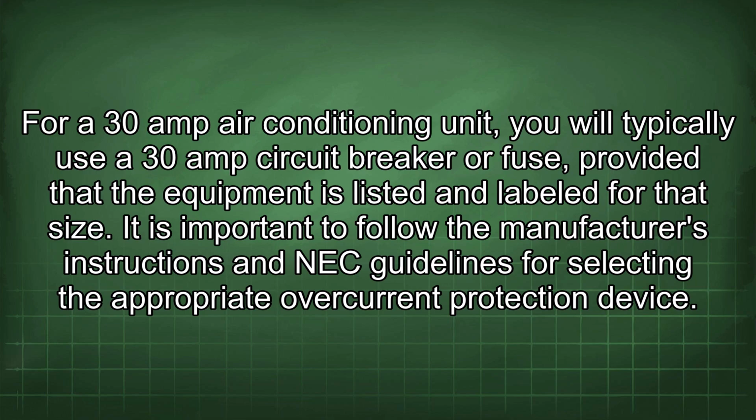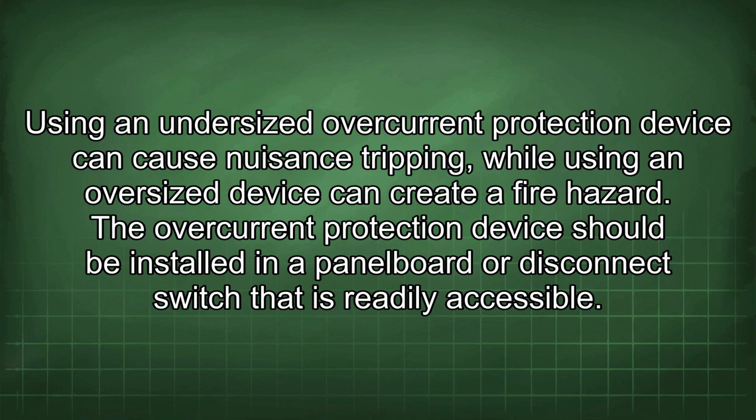the equipment is listed and labeled for that size. It is important to follow the manufacturer's instructions and NEC guidelines for selecting the appropriate overcurrent protection device. Using an undersized overcurrent protection device can cause nuisance tripping, while using an oversized device can create a fire hazard. The overcurrent protection device should be installed in a panel board or disconnect switch that is readily accessible.